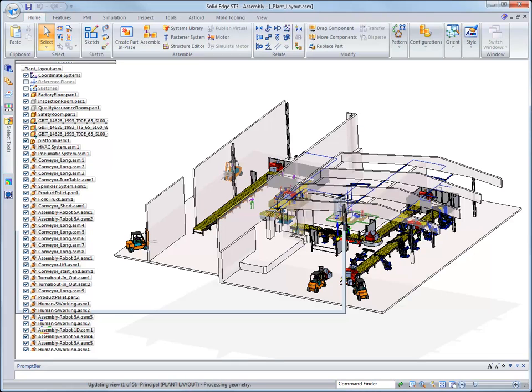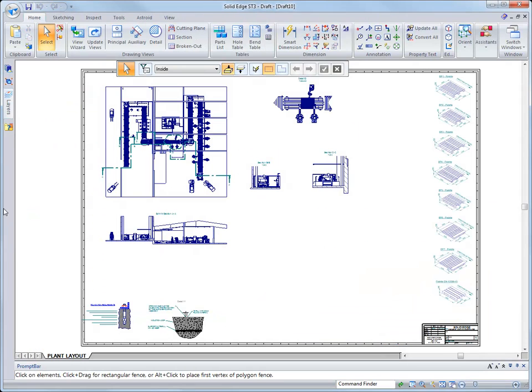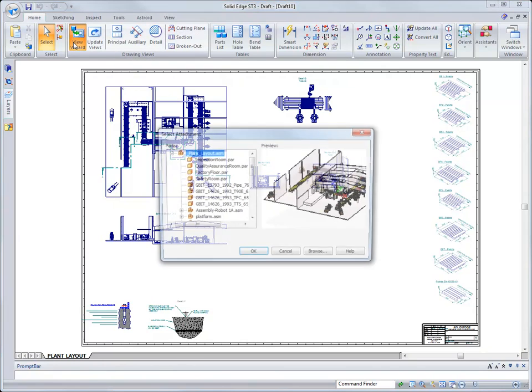Once the edges are determined, Solid Edge will apply the appropriate line symbology to them. It's not uncommon to have hidden lines dashed or even drawn in red. For this demo, we display the visible edges slightly thicker to better show the key elements. Quick Sheets, as you can see, are quick and complete, but sometimes you need to add additional views.